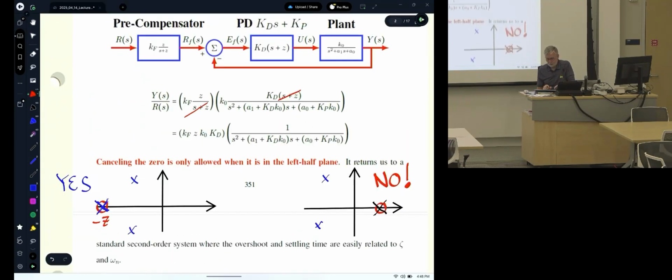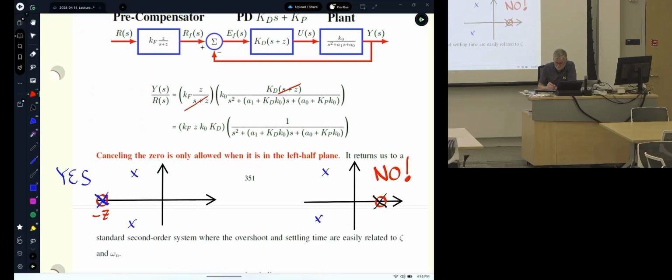Well, why is that interesting? Here, I took all the coefficients outside. These terms are setting the poles of the transfer function, but we've got one parameter left that we can tune. If we set this product divided by this number equal to 1, then the DC gain of this transfer function will be 1 as well. So this will vanish, we have this divided by this, and we just use that to solve for KF.